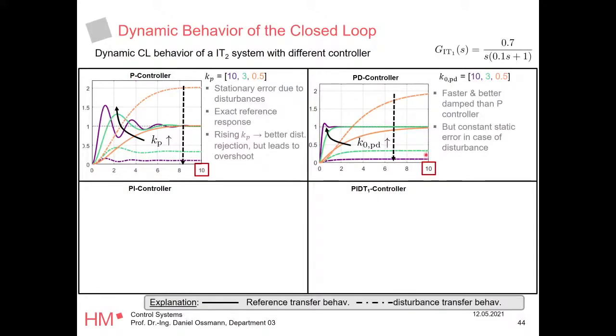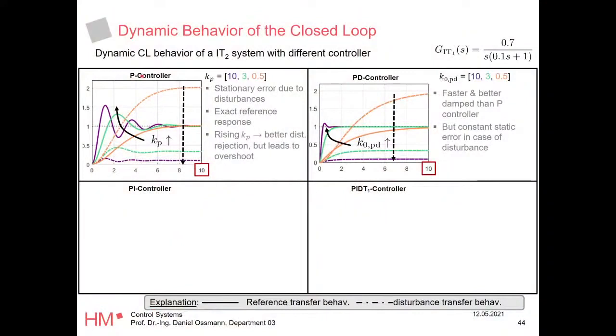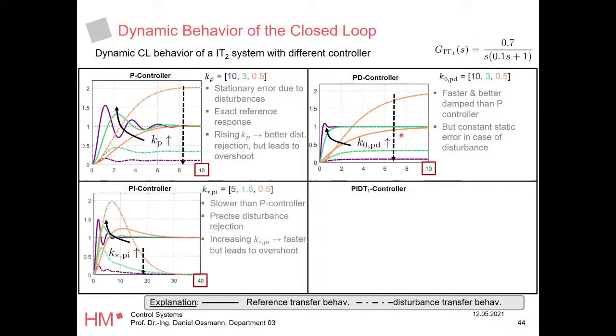So what do we do with the disturbance? Well, we definitely need an integral in our system, right? But we said, okay, a pure integral is not working. Why? Because two integrals are too much. Well, if you use a PI controller, we know a PI controller is faster than a pure integral controller. This actually is doing the job for us. So we add the fastness of the proportional controller and the accuracy of the integral controller. We fuse that and we applied it to our system, and suddenly we now have an accurate system in the reference tracking and in the disturbance attenuation.